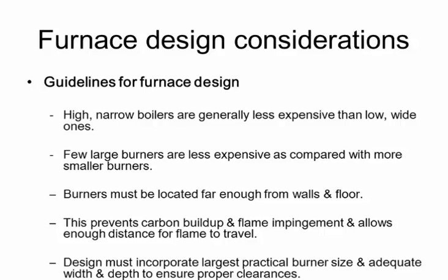Furnace design considerations. Guidelines for furnace design. High, narrow boilers are generally less expensive than low, wide ones. Few large burners are less expensive compared with more smaller burners. Burners must be located far enough from walls and the floor. This prevents carbon buildup and flame impingement and allows enough distance for the flame to travel. The design must incorporate the largest practical burner size and also adequate width and depth to ensure proper clearances.